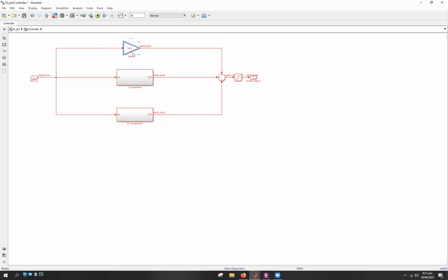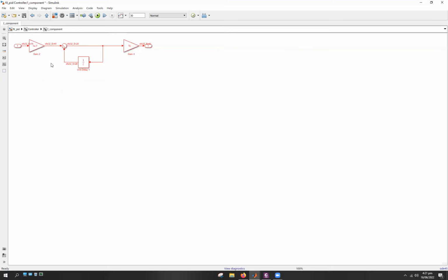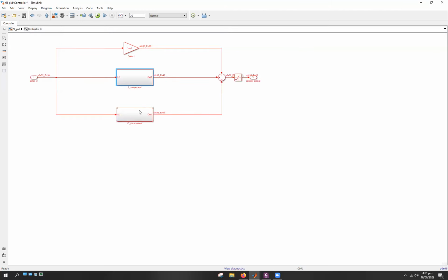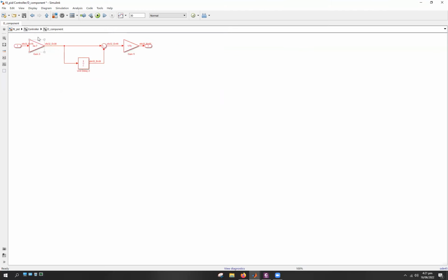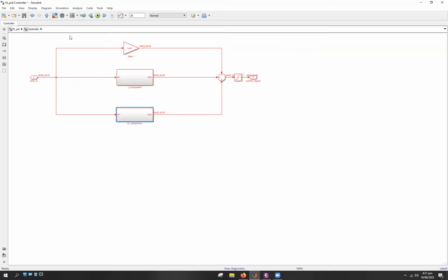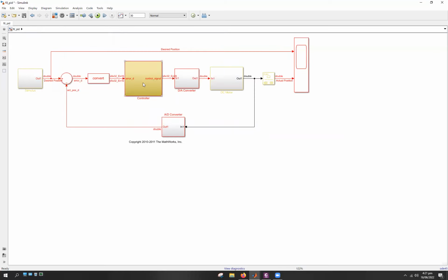For the PID, they have selected the gains right here, which you are seeing. For the proportional gain, we have this constant block right here. For the integral gain, we have the integral gain and then the integration constant, and similarly we have the differential block. Right. So this entire part is HDL compatible, meaning we can generate a successful HDL compatible block for this particular FPGA-in-the-loop setup.